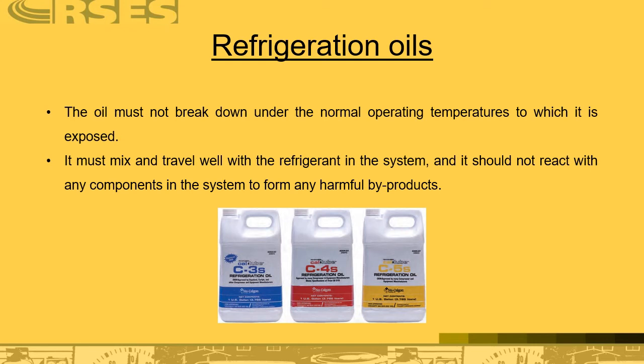Oil must not break down under normal operating temperatures to which it is exposed. It must mix and travel well, miscibility once again, with the refrigerant in the system, and it should not react with any components in the system to form harmful byproducts.